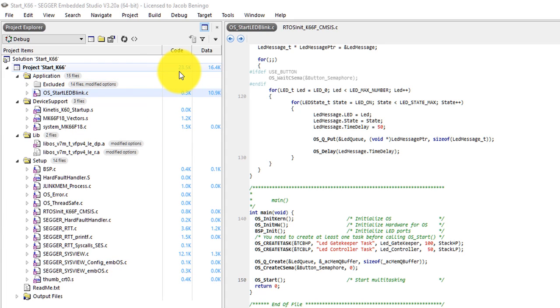is 23.5K, which might seem like it's pretty big for an application that doesn't do a whole lot. But as you can see, for a production intent system, we really wouldn't include these additional files that allow us to do real-time tracing of the application code. That would be a security risk. And as you can see here, the module that communicates with SystemView is 12.1K of code space. So out of that 23.5K, almost half of it is related to just being able to transmit up our data.